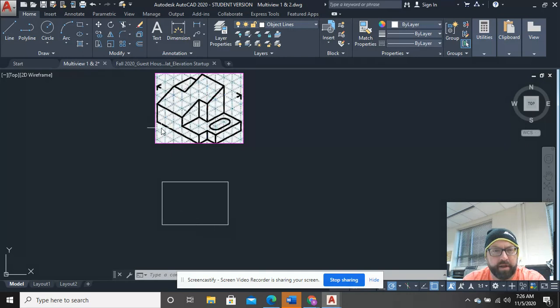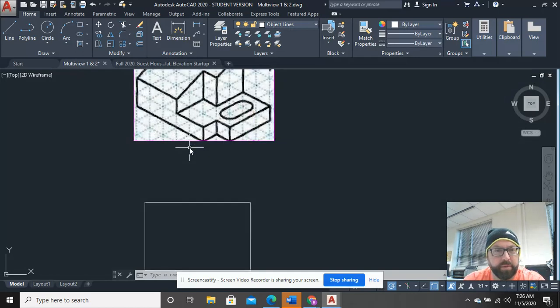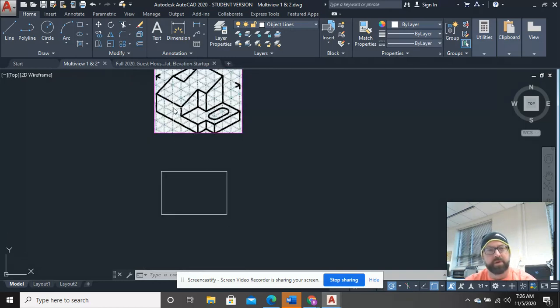And the front of this is not too bad because if I look, I have this front face that is up 2 and it's 3 wide, and then it drops down 1 and then it goes over 2. So I'll try this, and I'm going to just go ahead and use an offset. Remember, that's O space if you're using hotkeys. And I'm going to try to type in 2.